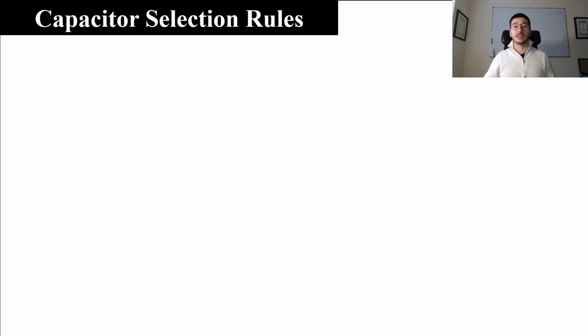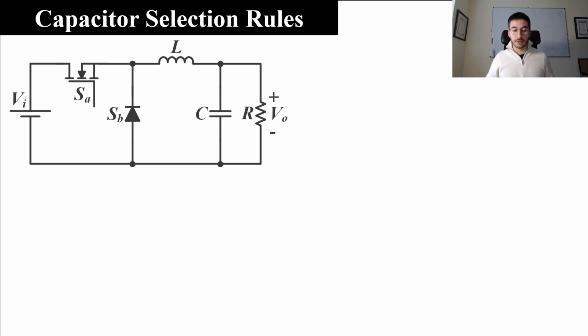We are going to choose the capacitor for our buck converter, and in this case the selection is very simple, because the capacitor will work in a very ideal way, taking into account the operating conditions of our buck converter. In this way, for instance, the power losses of this capacitor are negligible, basically because the parasitic resistances of that capacitor are very small.